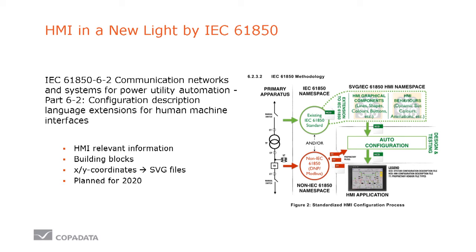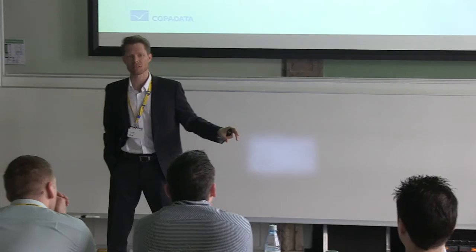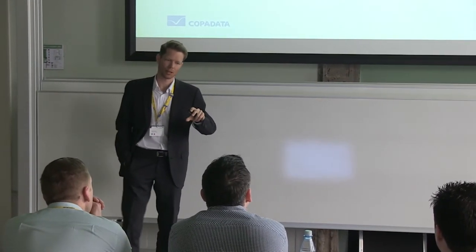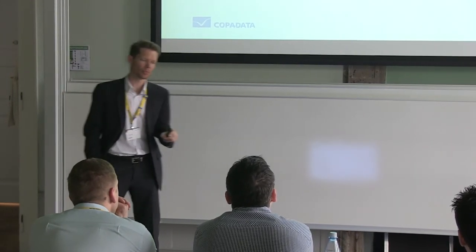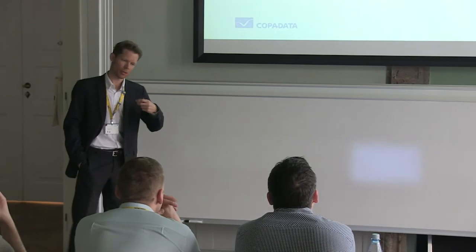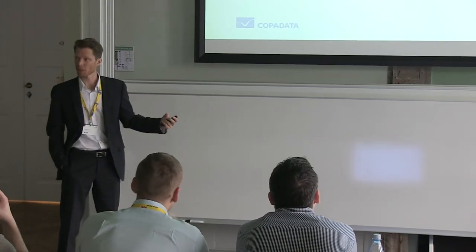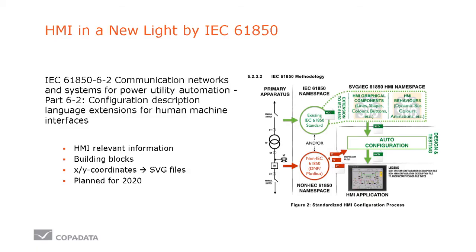In the past, 61850, from my point of view, was focused quite a lot on the server side, on the GOOSEs, not on the HMI. But there is this new standard which we are currently working on, which will be called IEC 61850-6-2.